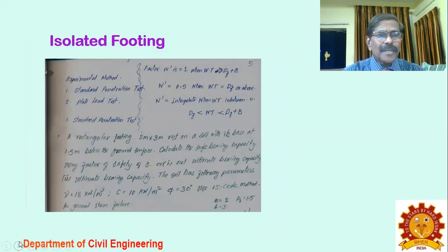There are some experimental methods also, the standard penetration test and the plate load test. The standard penetration test will give the number of blows, how much the soil can resist. Then from that you evaluate the bearing capacity of the soil.